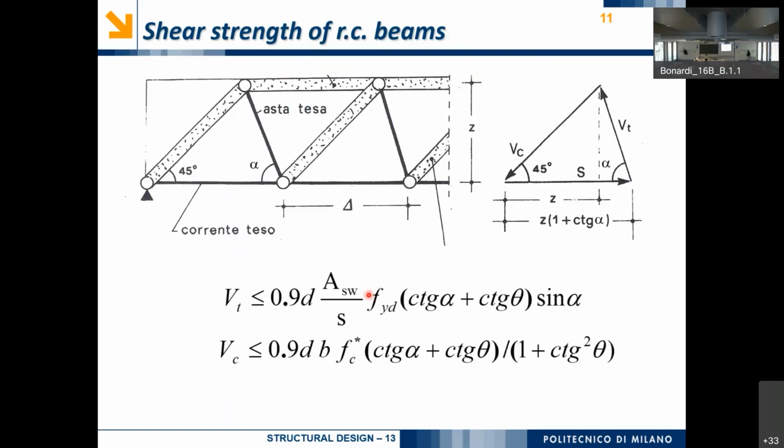I think, okay, this is the very last slide. The next one is basically the same. So far we have dealt with how to compute the forces in the upper chord and in the lower chord, knowing only the bending moment. But we are interested in what happens in this strut and in this tie, because we will find some values of resisting axial force in this strut and in this tie that only depend on the design, so on how big the structure is and on the quality of the material, obviously. But here we have much less freedom to design.